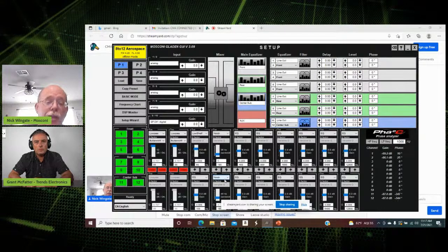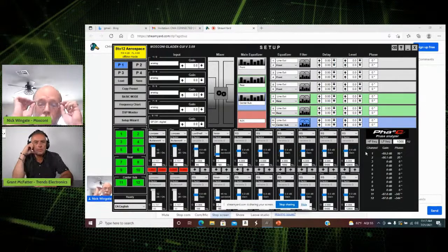It may not be 180 hertz. It may be 190 or 210 or 140. So that means you could go in here and change this out as well. That's how powerful this is. And this works in doors, mid-ranges, high-frequency drivers. Believe it or not, sometimes a tweeter will reflect off of the dash or reflect off the windshield, and you get this really nasty spike with a tweeter.